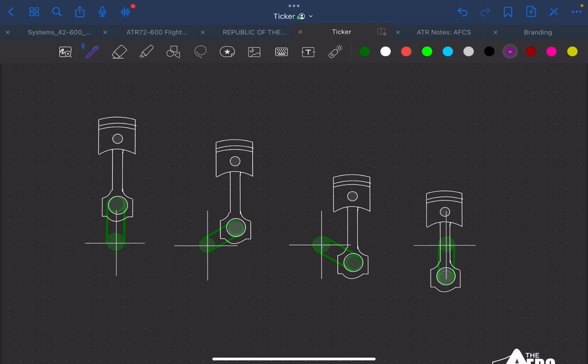Remember, in the discussion for reciprocating engines, we understood that the rotation of the crankshaft determines the timing of the sequence of the movement of the piston and the entire engine. It determines the firing sequence. It determines the intake and exhaust valve sequence. Basically, again to emphasize this, the crankshaft controls the entire sequence of the operation of the engine.